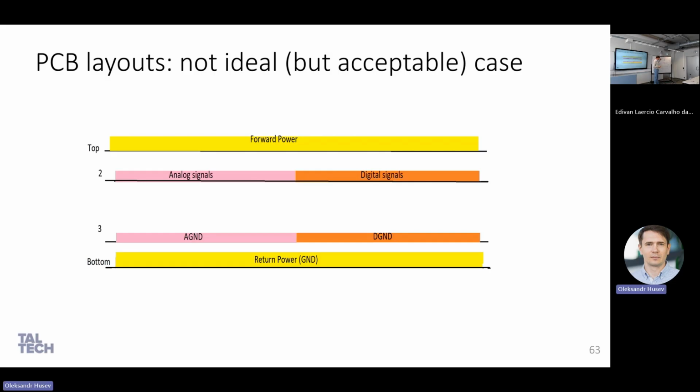And it could be achieved in several ways. Of course, you can put extra capacitors. Then, if you're talking about layers, definitely make overlapping of these layers. It will just create an extra capacitor. It's good. Just use wisely the copper that you have.